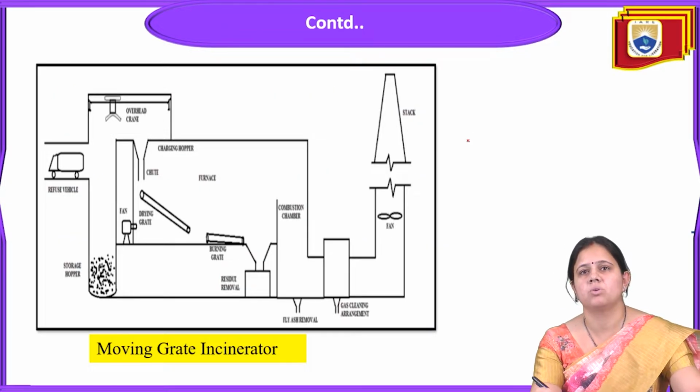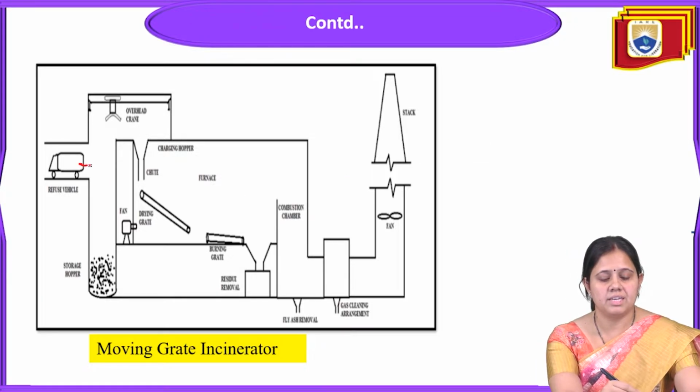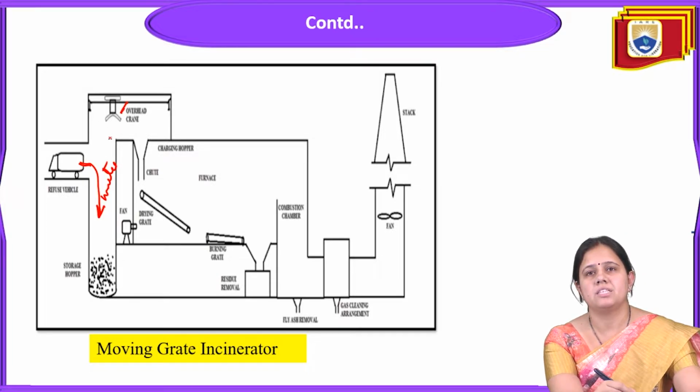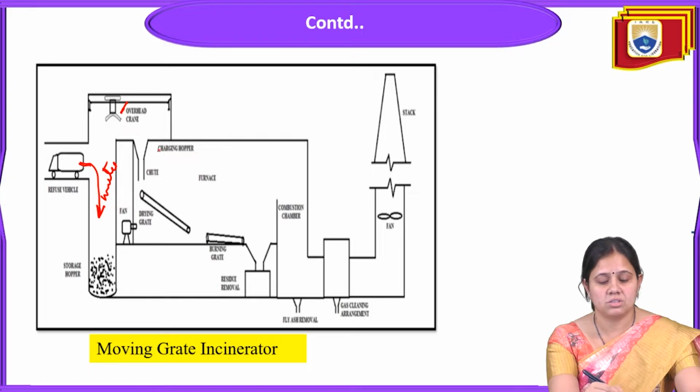When we discuss the designing of this moving grate incinerator, you can see the vehicle is bringing the waste, and here the overhead crane is there. That crane is pulling the waste and putting it into these chutes, and by the chutes it will enter the drying grates.